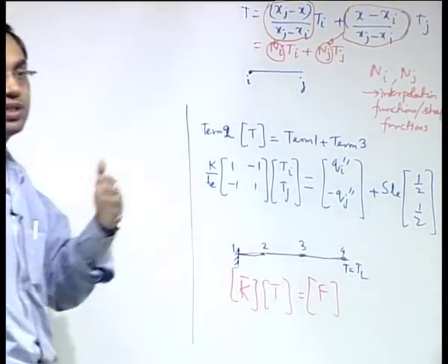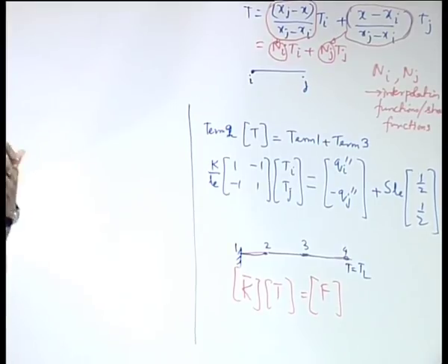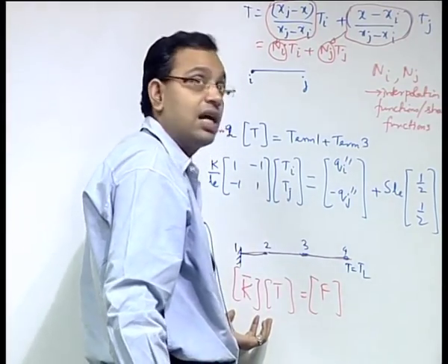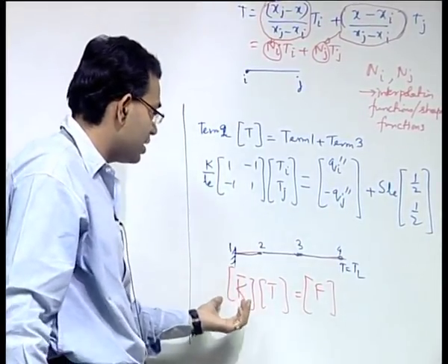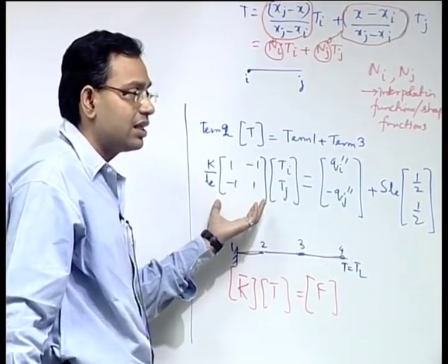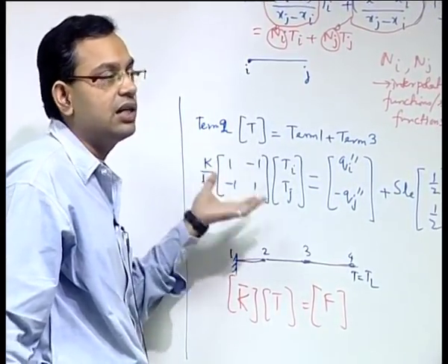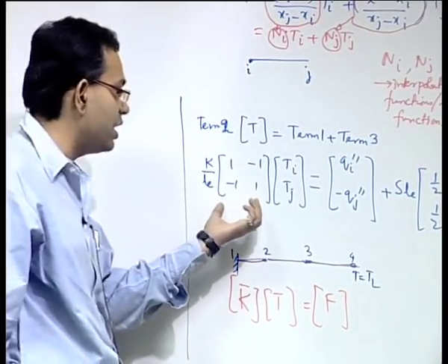So it is almost like a spring mass system, and the reason this analogy with the spring mass system always comes up is that the finite element method was originally developed for structural mechanics by engineers. It was not originally developed for solving heat transfer and fluid flow problems. So still this type of matrix is known as a stiffness matrix, but we need to keep in mind that it is just a nomenclature. It has nothing to do with the stiffness in a heat transfer problem. The physics of heat transfer of course has nothing to do with stiffness.